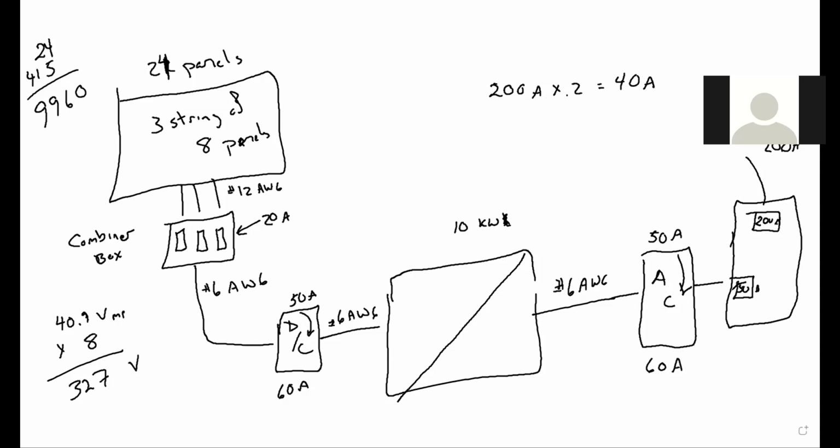All right. And we're wanting to come in with 50 amps. So that will present us with a problem. This system is too large to connect load side connected to a 200 amp box. Now, if it turned out that the bus bar rating was 225 amps, which sometimes you'll run into, well, then we could go up to 65 amps, the 120% of 200 plus 25 more, and that would be okay.